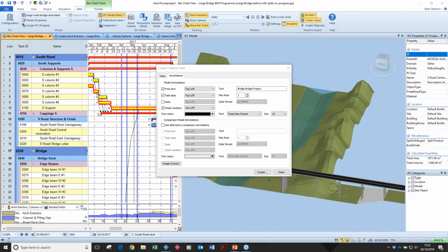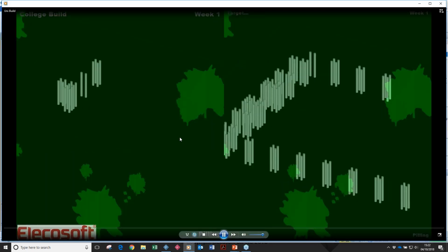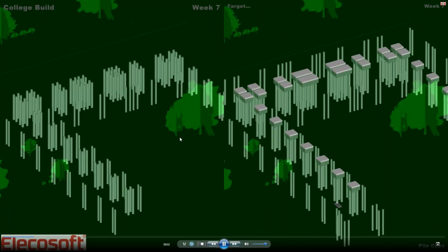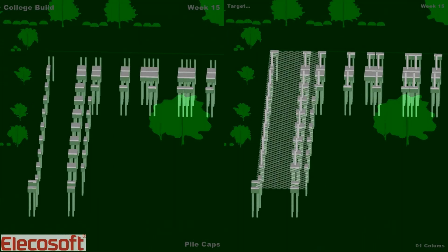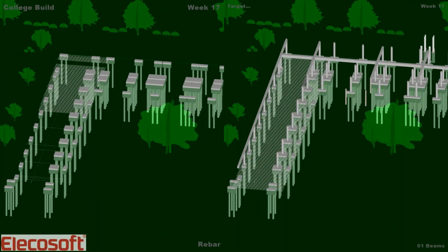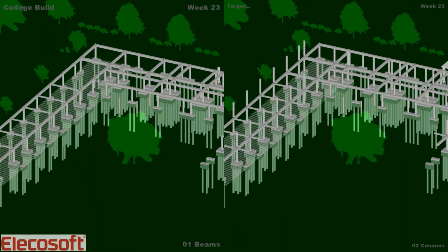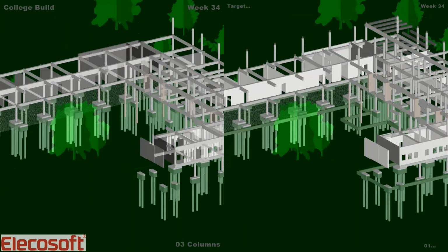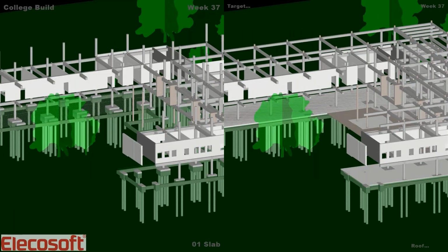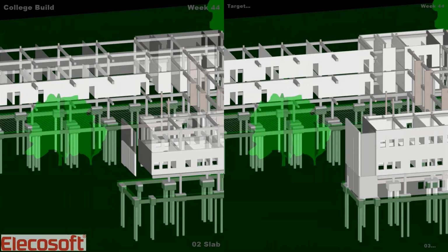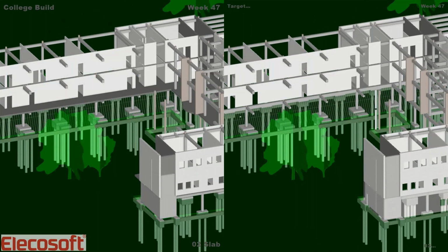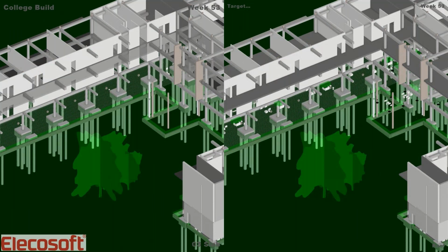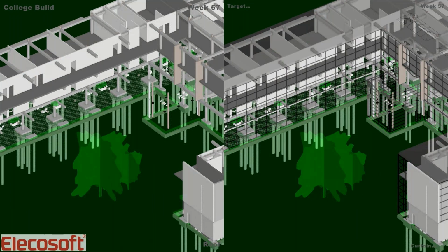Let's go back to the university buildings, because in this example, I've got the baseline showing. So this is just playing in my Movie Maker. Again, it's compressed at your end, it's smooth at mine, and it's showing me the tasks I'm working on at the bottom. It's showing me the annotations across the top, including the week numbering. And one final thing I did was actually drop the company logo on as well. So within the video overlay window in Powerproject BIM, I've got all of the controls I need to create these and many other typical videos.